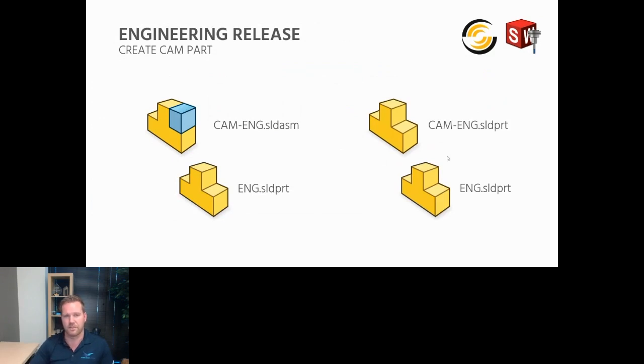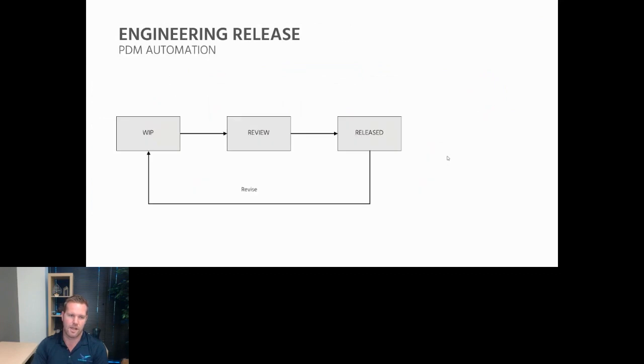So we have all the benefits of using all your standard part features in the SOLIDWORKS environment, adding, removing material, Hole Wizard stuff, etc. Giving the machinist the capabilities to manipulate that geometry however he or she needs to for the machining purposes.